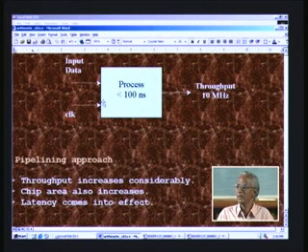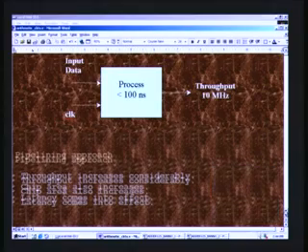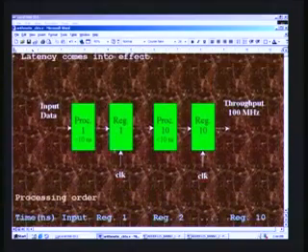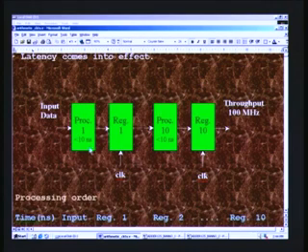It is a mere question of dividing the entire process strategically. Let us say we have some 10 processes, and each of these takes roughly 10 nanoseconds or less. If you add all this, it amounts to 100 nanoseconds, which is the same as the original process, and what we are going to do is just divide this process 10 times. So we will have process 1 taking less than 10 nanoseconds, then process 2, and here I have put a dotted line implying that similar blocks are there for the rest.